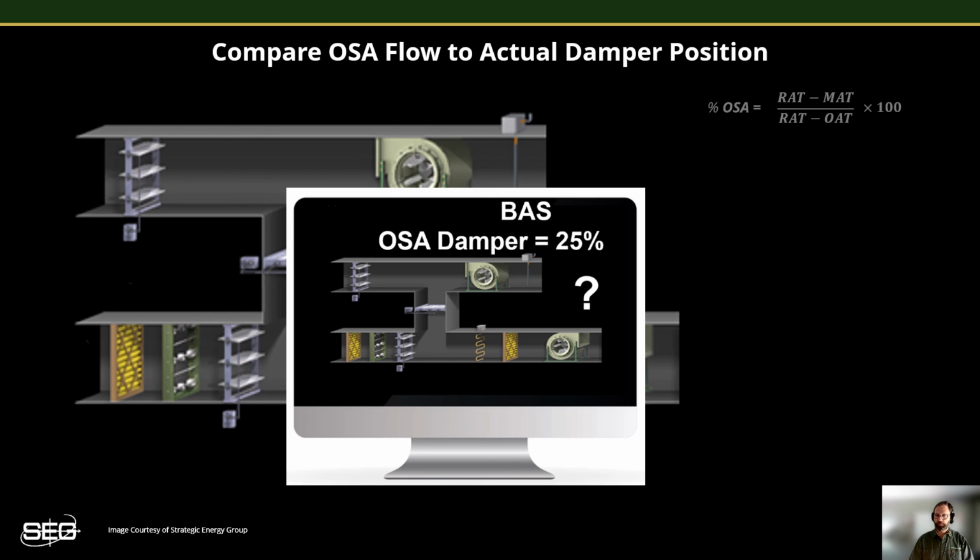The point being, when the EMS has commanded the outside air damper to its minimum ventilation set point, you can't automatically perceive the displayed value percentage as the actual position. My recommendation is to use one of the previously mentioned methods that measures the actual flow and then compare it to the EMS's displayed percentage. Then adjust the EMS's minimum ventilation set point as necessary.